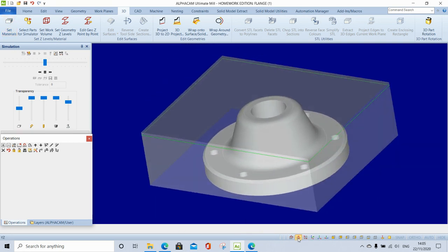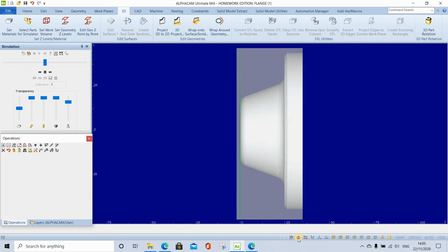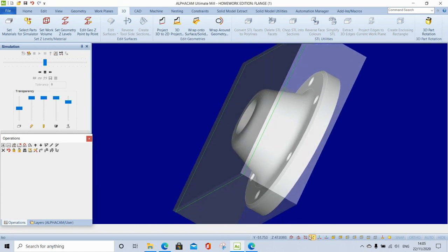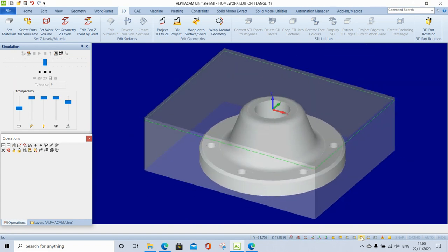So I can also view this way, which is a grid reference. Okay, so -35 is at the depth of the part. We can see zeros here. This is +2 because I'm going to machine that 2 mil off. Okay, actually go top view.